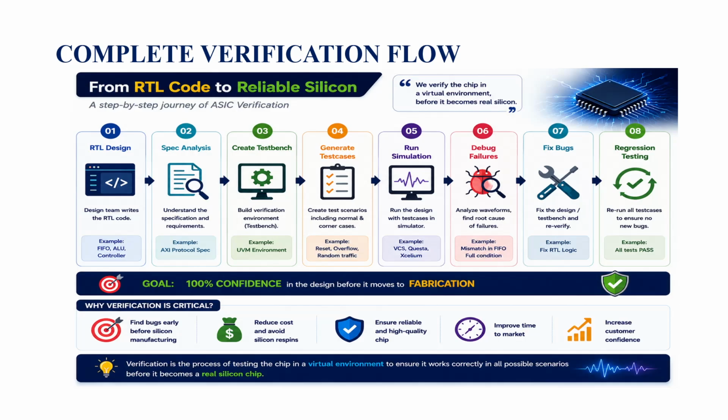In the simulation we have 3 steps: one is compilation, another is elaboration, and the last one is simulation. Compilation means we check that my code is free of syntax errors. Next is elaboration, where we check whether all the components have been connected properly, and I print the hierarchy, the topology. And the last one is simulation, where we print the output for that reset test case. These are the 3 phases in the simulation.